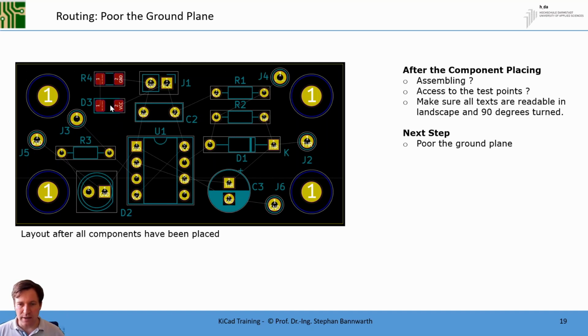After having finished these placements, you should ask yourself some questions. First, is assembling possible? For hand soldering this is not so important, but later for production of series products it's very important. But for us, what's important is: is it possible to access all test points?